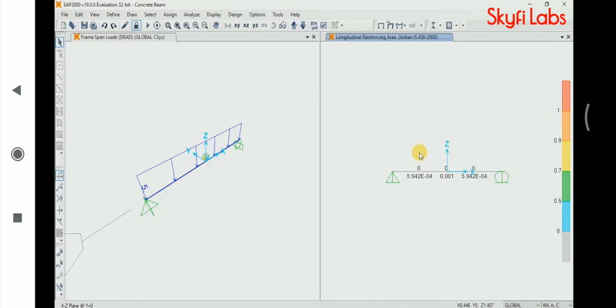The values indicate the ratio of stress carried in the frame to its maximum stress carrying capacity. A value more than 1 indicates stress more than its capacity. This would result in failure of the beam, and the beam would then be colored in red. Here the beam color is not red, so the beam is safe against stress.